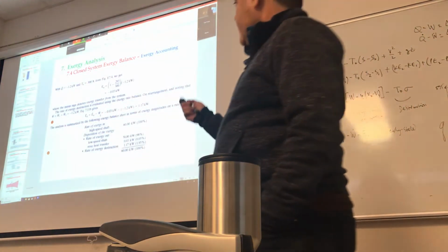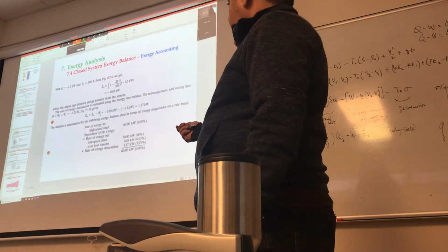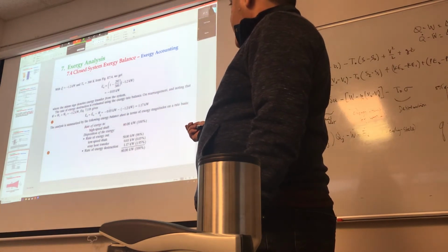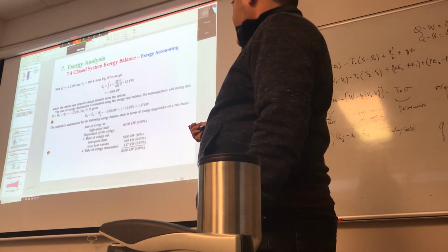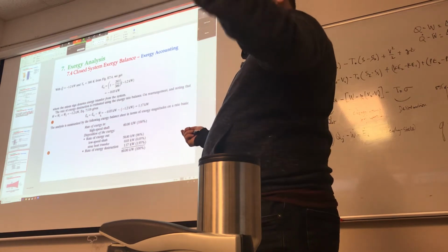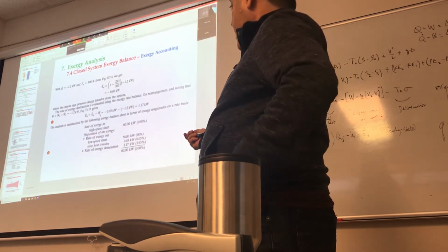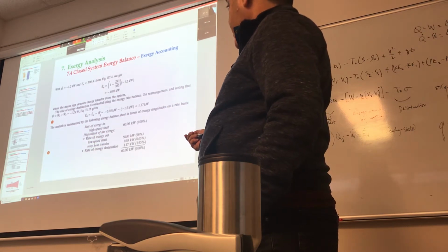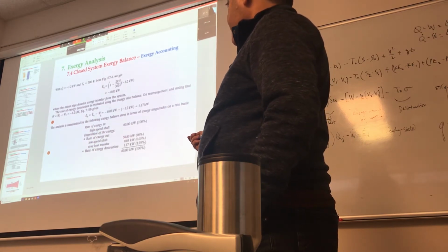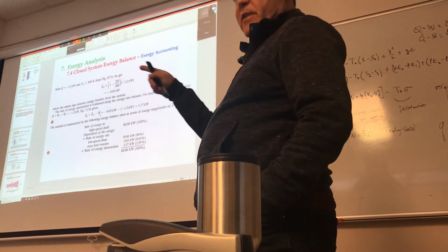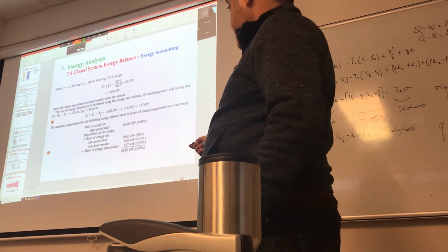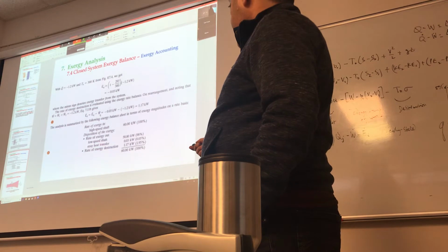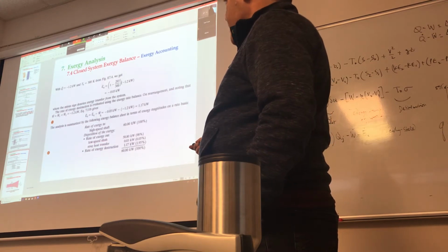When you do an accounting of this, you go like, okay, what is the rate of exergy that's coming in? It's obviously 60 kilowatts coming in because that's the input shaft, right? How are you disposing of that exergy? Well, the rate of exergy out is 58.8 because that's what the power output is bringing in, through the low speed shaft.